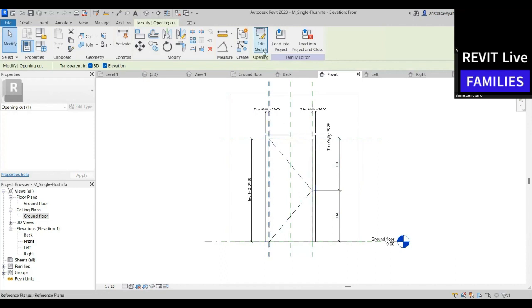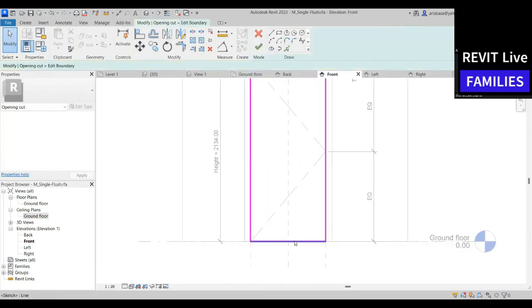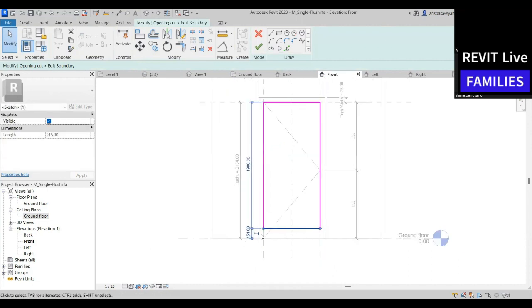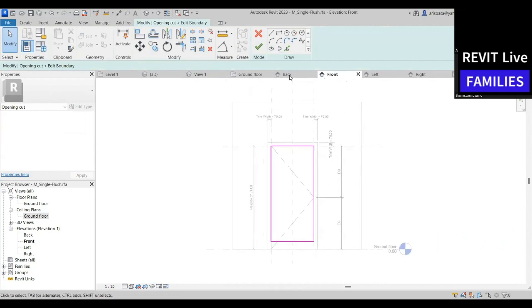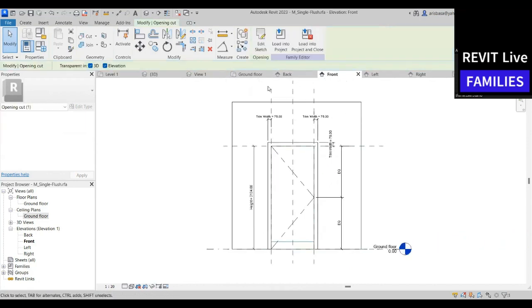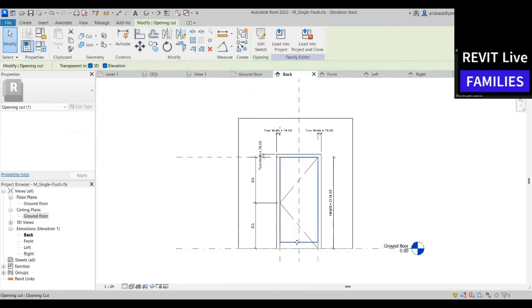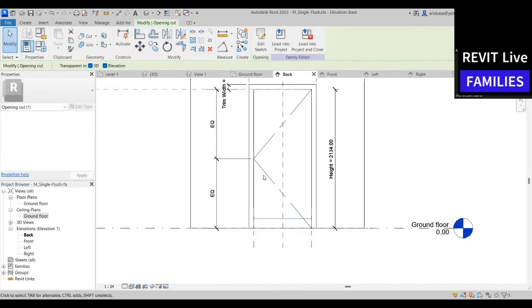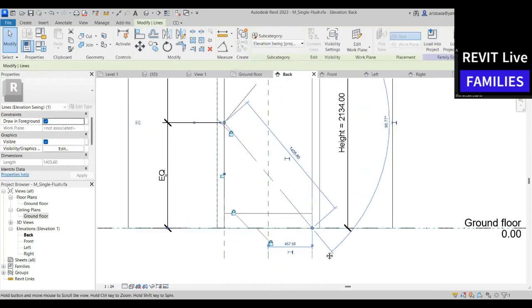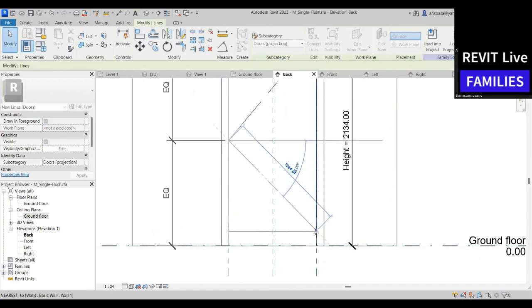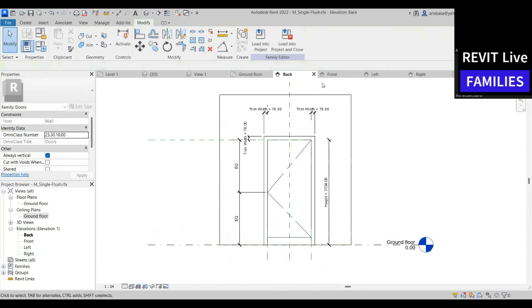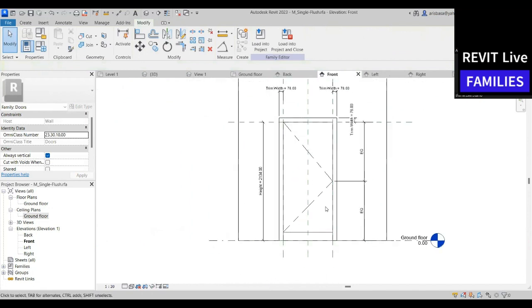Edit the sketch. And then lift it up by, let's say, 150. Make it 150 exactly. So that is the front. Make sure that you go to the back, that it's the same. So it's now the same. But of course, if you are very much concerned about doing the correct lines, you want this to be moved here in terms of drafting, to also move the upper part.